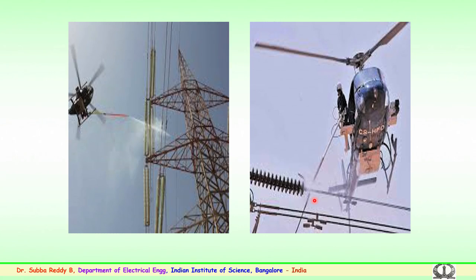It could be a fixed type, or pilot controlled, or a second person who is on the controls and directs the spray to the insulator for proper cleaning. Several of these methods are being used presently for live line maintenance in some conditions, and also for de-energized conditions in the case of cleaning.